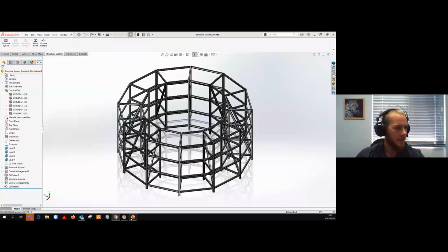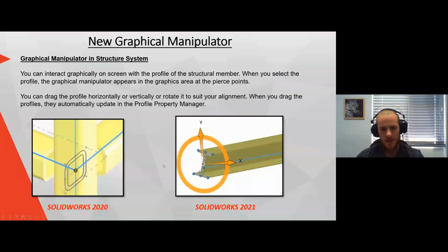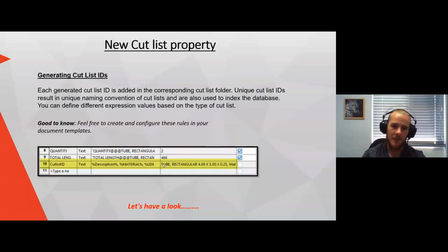So just to carry on where Pierre basically left off. As mentioned, cut lists come into play when we deal with weldments and sheet metal design. So please don't forget that Cutlist ID can be found under Tools, Options, Document Properties, Weldments. Go and put it on and check it out in your sheet metal and weldments design. Please feel free to get in touch concerning any support questions, perhaps any how-tos. We are able to assist and provide information to get you going.